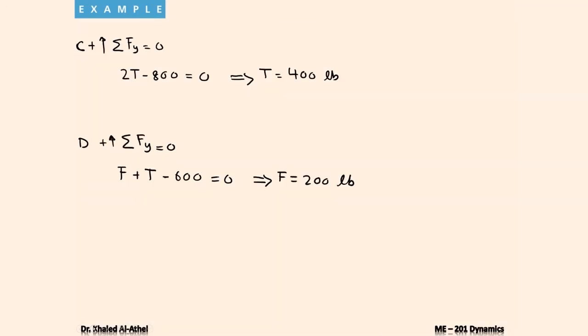So finally, I will write that F times Vd, which will equal 200 multiplied by 8, which was given. So this will give me 1600, and the unit is foot-pound per second. And this is your power that is required, that is fed into the motor.